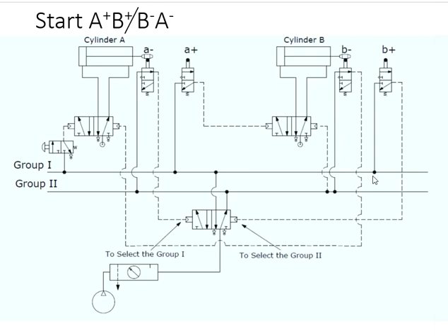The key important point you have to note is every cylinder should have one DCV. Since it is a pneumatic circuit, we are going for 5/3 DCVs. And at the end of this cycle, whatever the sequences are, for example B minus means cylinder B is in the retracted condition, A minus means cylinder A is in the retracted condition.